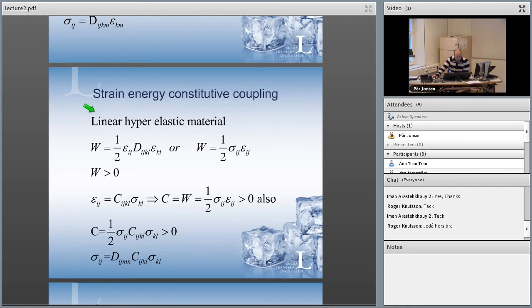We know that we can rewrite this one now like this. We can find the strain energy by taking this relation. But this is only valid for elastic material, linear elastic material. So half of the energy that you see in the graph is the strain energy. The other part is the complementary energy. So it's just a straight line in this case. So you can also write it like this. But you know that energy is always positive in this system. You don't have negative energy for the system. So this is one criterion that you have to fulfill in your model.